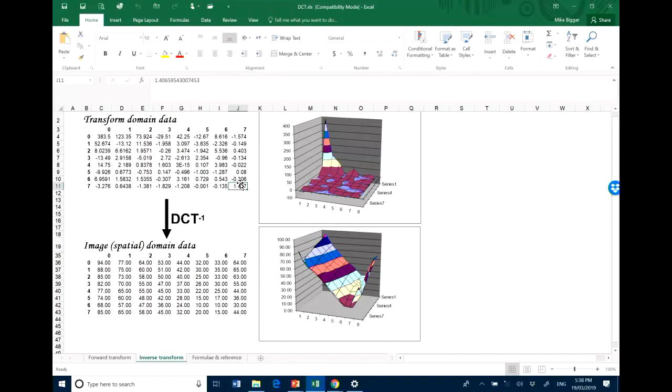coarsely quantized or zeroed all of these small values. And what we're interested in, of course, is this reconstruction here. So if I take a little time, hopefully not too much time, to just very coarsely quantize that transform data, we get a bit of a feel for how effective the DCT is in preserving and approximating the important information.